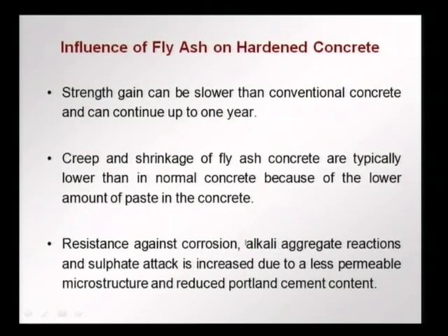Finally, what is the influence of the fly ash on hardened concrete? The strength gain is slower. So, the concrete can take more time to reach its strength. On the other hand, you can think of it as a buffer strength which is there in the concrete even after 28 days. There is an additional concrete strength gain even after 28 days.